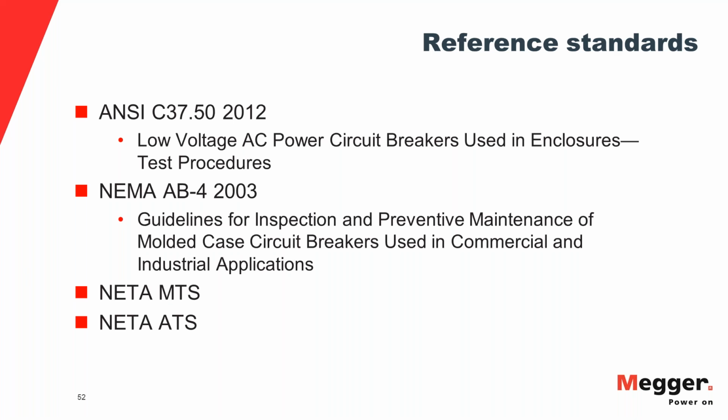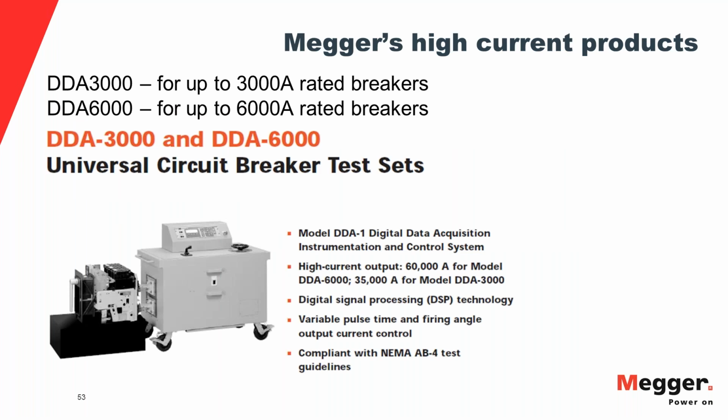As far as high current testing goes, there are all sorts of breakers. They come in various shapes and sizes. So depending on your requirement, you would need to use different test sets, right? When I spoke about then versus now, then doesn't mean that the technology is obsolete. The technology is very much relevant today, because in cases where the breaker capacity is very high, the traditional technology has worked for decades and it will continue to work. Efforts are being made to get the test sets with modern technology to work at those high current levels.